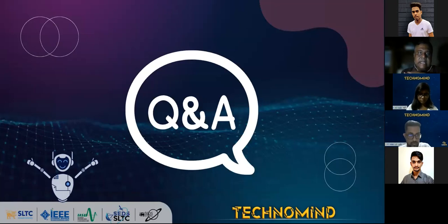In that case, I believe that Gazebo is better because when you use Gazebo, you can keep your software separately, as I explained earlier. So you can write your software, test it on Gazebo, and then put it on the robot without any major modification to the software. Therefore, although there are other simulators like VREP, Microsoft Robotics Studio, and so on, ROS and Gazebo may be ideal for your competition, I believe. That is more general, and it is more flexible than the other ones that I know.